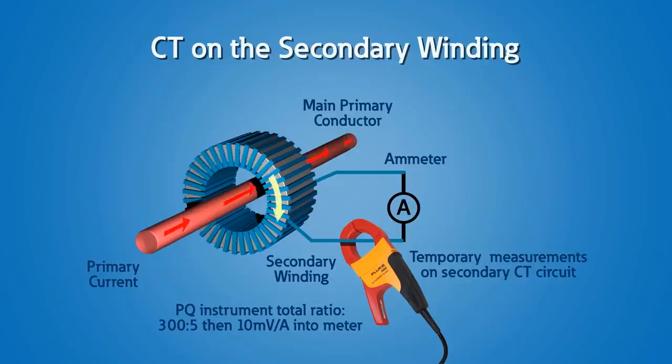With this resistor, these CTs typically have a rating of 10 millivolts per amp or 100 millivolts per amp. The lower range ratio is usually used for secondary measurements, in other words, clamping onto the 5 amp secondary of another CT. Sometimes the current value is too small.